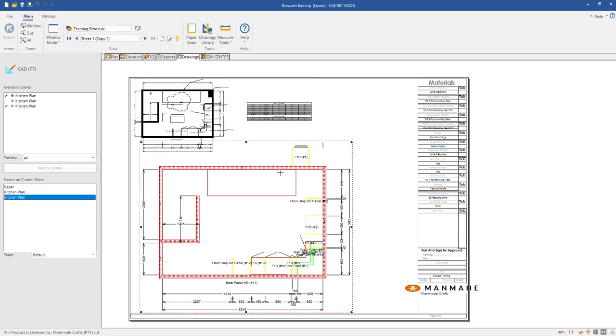Just be warned, if you use multiple live drawings on multiple sheets, it's going to slow it down quite heavily because it's basically multiple instances. The designer will only do that if they're busy with the client at that point in time, making quick changes and getting the information on a template, and if they want to send that through to a client. Otherwise, use static images. It does slow down the system tremendously if you have too many live drawings.